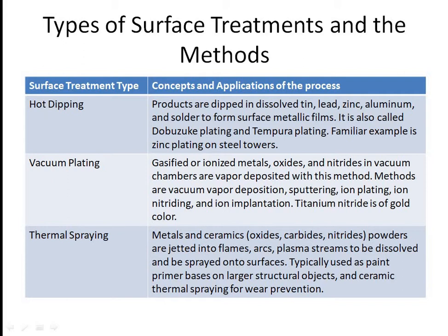Now the next part, we will see what is the meaning of vacuum plating. Vacuum coating or plating is a technique for surface coating in a vacuum or in a vacuum chamber filled with air or an inert gas. At present, the three main methods of vacuum coating have many characteristics such as no pollution, no hydrogen embrittlement, suitability for a variety of substances and a relatively simple process.